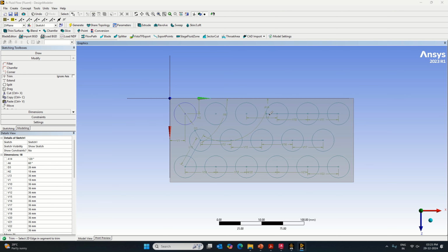The purpose of drawing the lines is to make sure that the distances are the same and the things are done accurately. Somebody might have used the copy options also. That is also one shortcut we can do. But the copy option sometimes makes an error in terms of intersecting edges or additional edges which are present. So you might not be in a position to extrude if some edges are there. So this is what we have done. We have prepared all these cells.